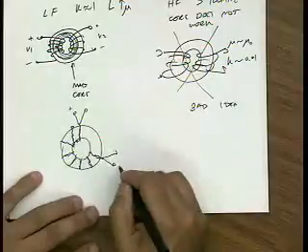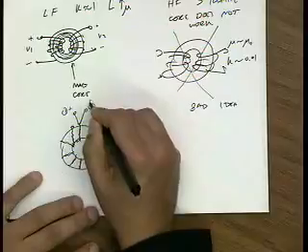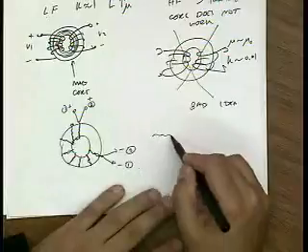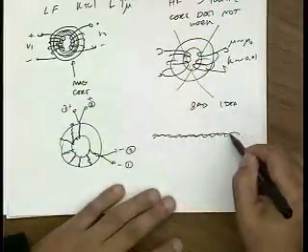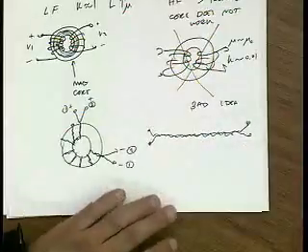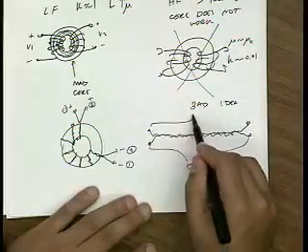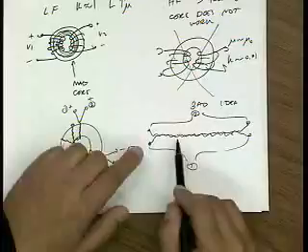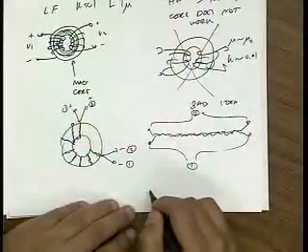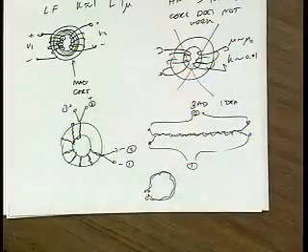So this is actually plus minus. So this is the primary of 1. This is the primary of 2. Okay. So what I've done is I've taken 2 wires and just twisted them together and formed a transformer that way. Okay. So really this is port 1. This is port 2. So I need to bend this to bring these 2 leads close together, right? So that's why I actually would bend them together to produce a transformer like that.